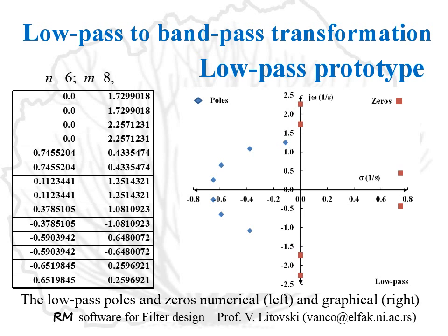Here is an example. On the left-hand side is a set of zeros in the top part of the table and poles in the lower part of the table of an eighth order filter with 6 transmission zeros. 4 of the transmission zeros are on the omega axis and 2 are complex.